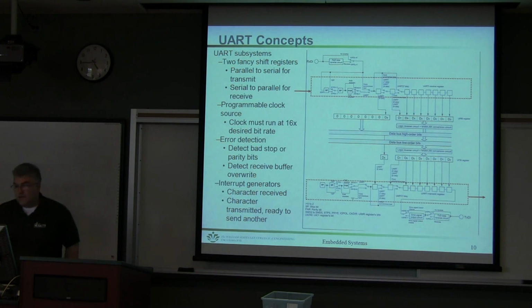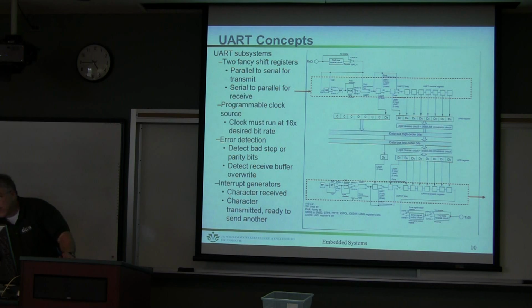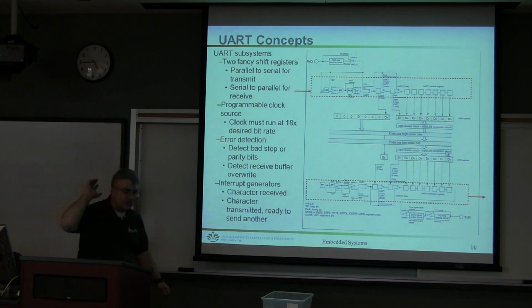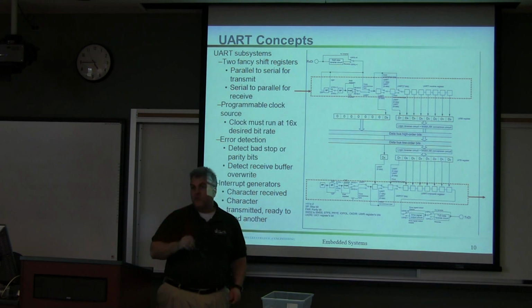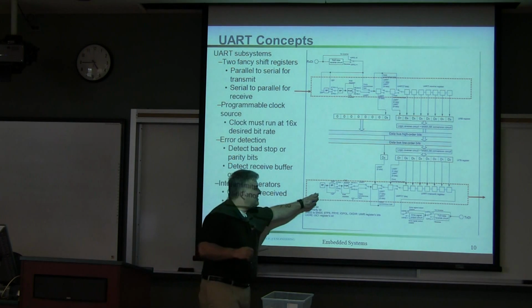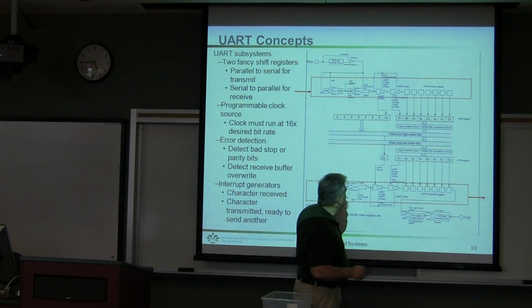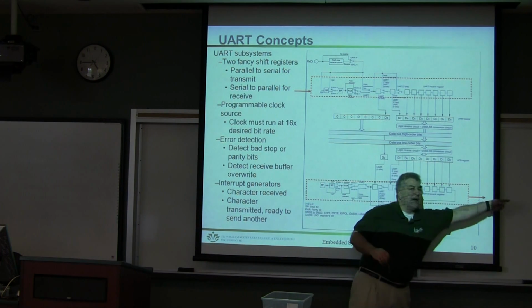So, literally, all you have to do is say, here, I'm going to write at this location, some memory location, I am going to put out here 8 bits of data. I'm just going to write a byte to a specific peripheral interface port. Then the hardware itself will add the parity, it'll add the stop bits, it'll add a start bit, and it'll send it out.